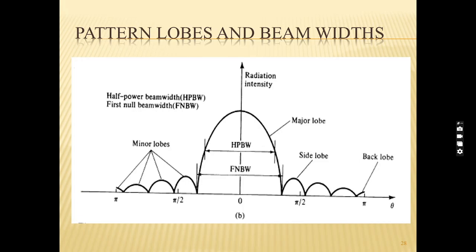Normally in practice, the three-dimensional pattern is measured and recorded in a series of two-dimensional patterns. However, for most practical applications, a few plots of the pattern as a function of theta for some particular values of phi, plus a few plots as a function of phi for some particular values of theta, give most of the useful and needed information.